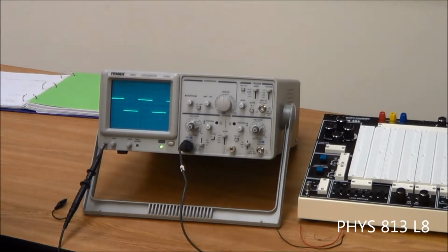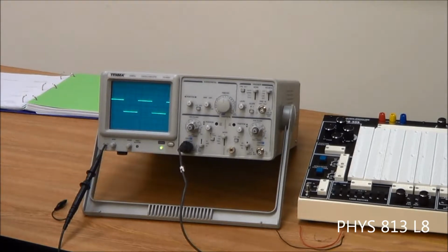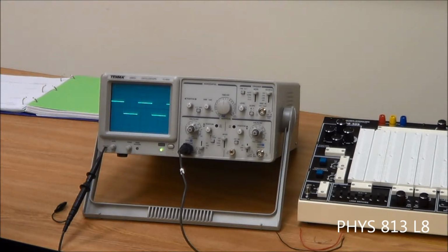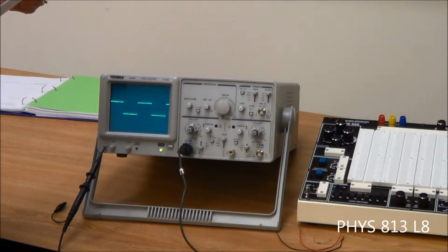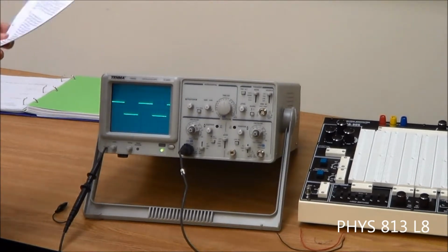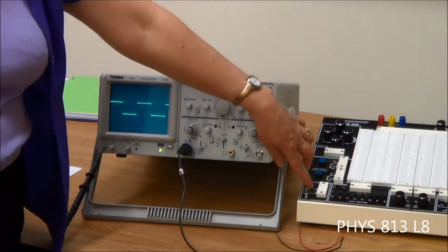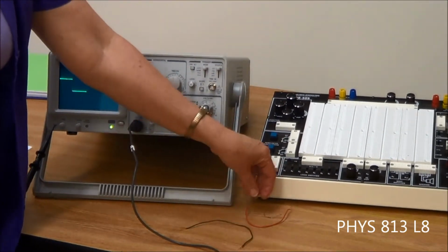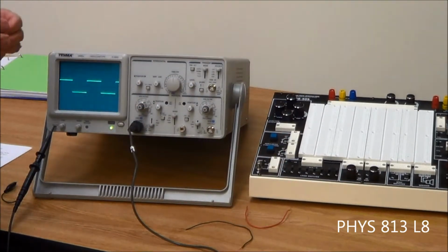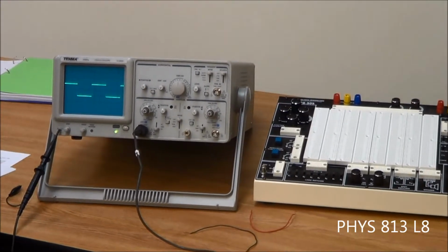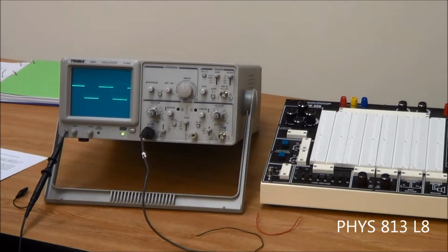Okay, so now we want to look on page 65, and I'm not going to go through step number 4 in detail. I'll just show you what it is. And I've already talked about number 2 and number 3 up at the top. So number 4, we want to build a circuit to determine the frequency of a wave. Okay? So this says to locate the ground in the lower left-hand corner here. You're going to need 2 wires, a few inches long, and then you will need the 5.1 kilo ohm resistor, which is green, brown, red.